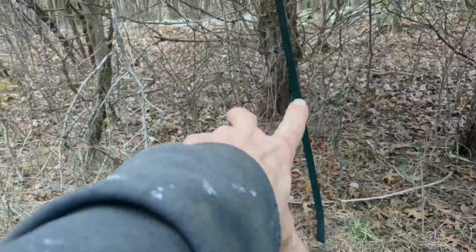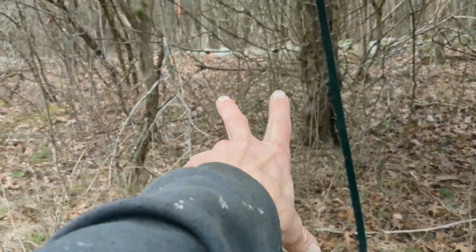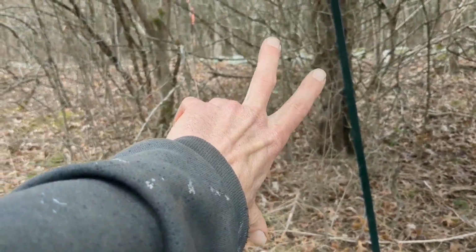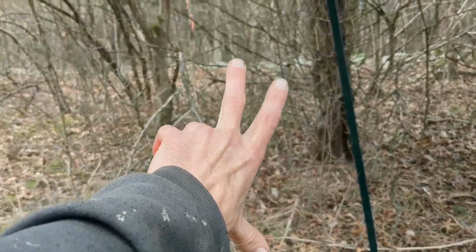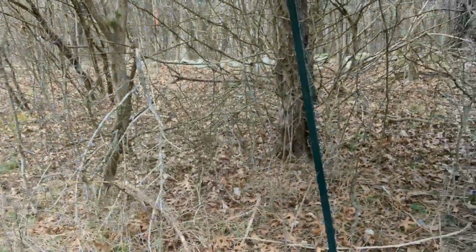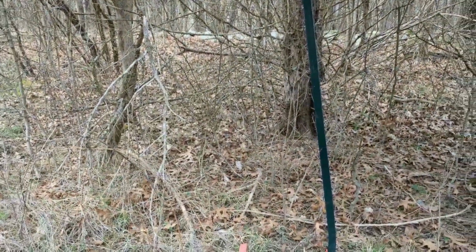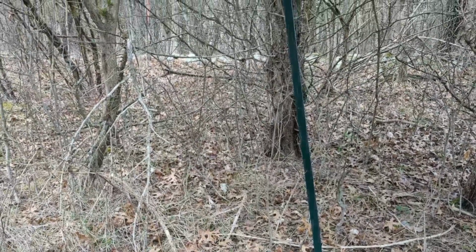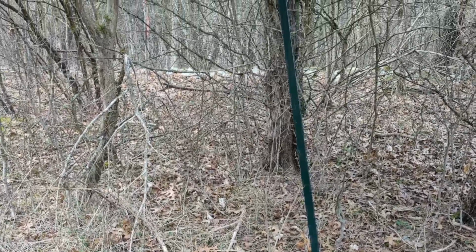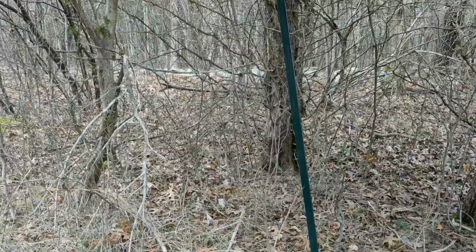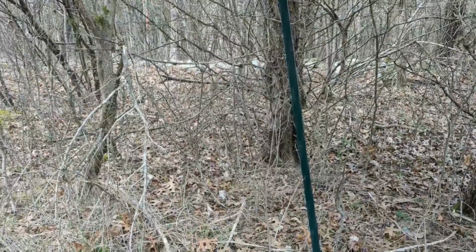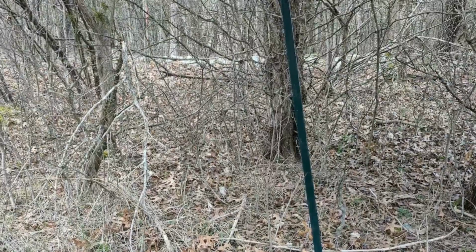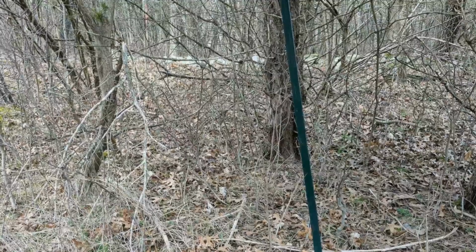And then as we take aerial photography and we rotate it to match north and other mapping systems, we can rotate it perfectly and we can scale it perfectly to imagery to make it fit in and work with our system. And then we have exact, precise data, aerial imagery overlaid, and elevation datum all in one base file. From that base file, we can develop layers and design and stake out. We can figure out how much cut fill we need, how high things need to be, how big they go, how far from property lines we are, and on down the list, including drives, septic locations, you name it.